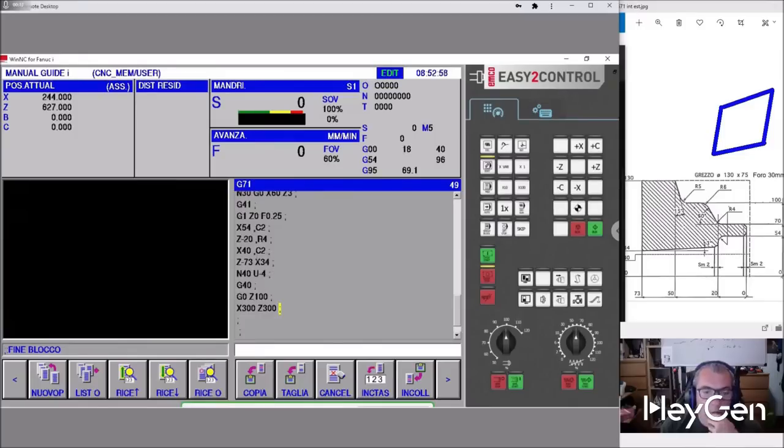To do the internal finishing, we need to position ourselves quickly at this point because of the point where it will return. If we position ourselves quickly at a point like this, after finishing the roughing, the machine will return in this direction, so it will cut my program. That's why now we'll write G0, Z3, X30. Then we'll insert my finishing macro with P30, Q40, and G0, Z100 when we're inside.